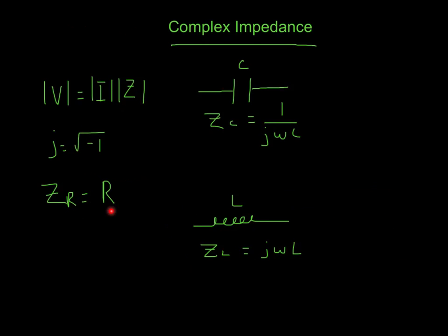With the resistor, we spend energy into heat, and with these we redirect signals, either across or divert them to another part of the circuit. The signals will reflect off here, or their phase will be changed in some way that redirects them. So it's as if these things impede. They do impede the signal flow or the current, but they don't spend it. Let's look at how these work as a function of frequency.